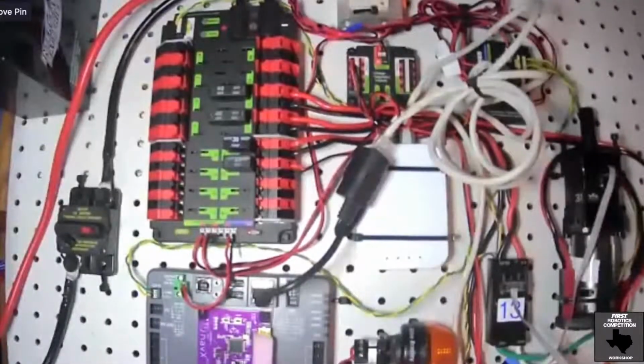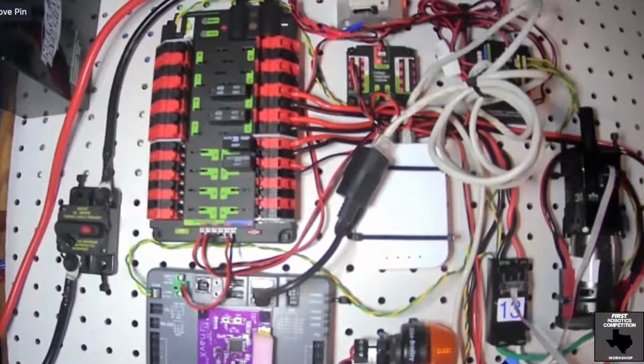Yep. And so with that, again, because amps are pulled and drawn by the motor, having a breaker that's too high won't do you any damage, because if you never hit that amount of current being drawn, it's not a problem. Having a breaker that's too low, if you go past it, you won't be able to do what you need to do.